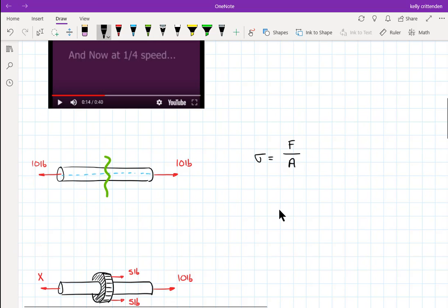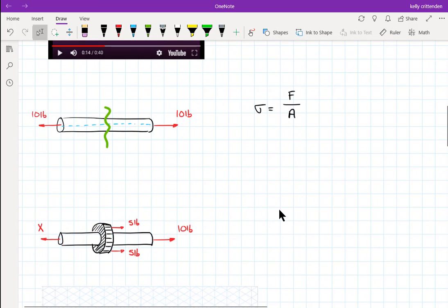And it is obvious when you actually take your bar here, make some line that you're going to cut through, and then draw it. It doesn't matter which, let's draw this side. And then we cut on this little surface right here. So we cut that open. So the internal force is on that little blue area. So here's the external 10-pound force. And then for this piece to be in equilibrium, it would need 10 pounds going this way. And so the internal force is only 10 pounds.